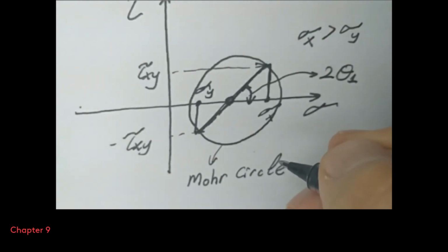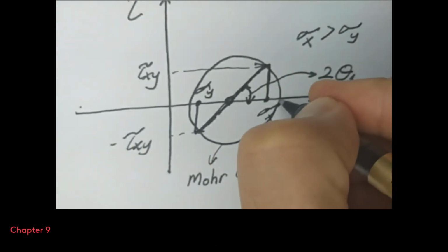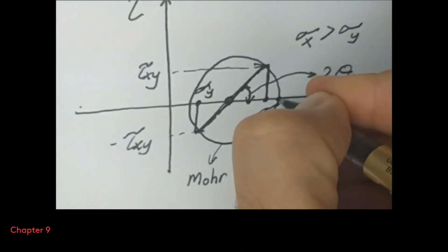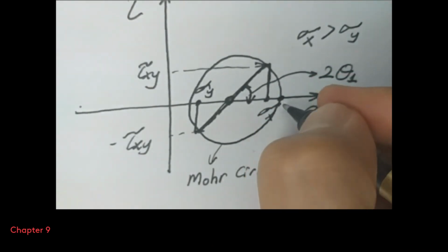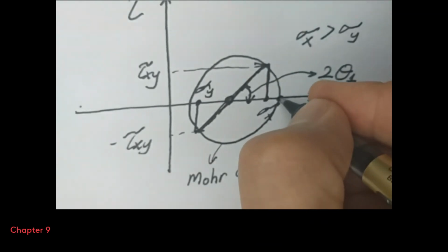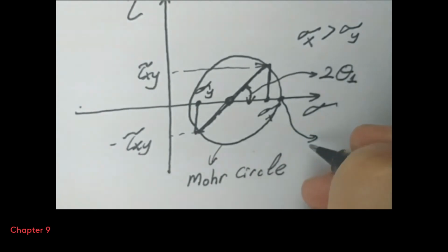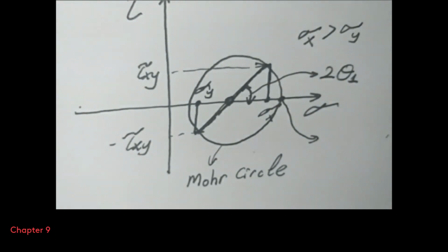Principal stresses are the stress values at which you have the maximum and minimum normal stresses, and in fact at these points you don't have shear stress. So basically you are looking for the location at which the shear stresses are 0. This is what it means.